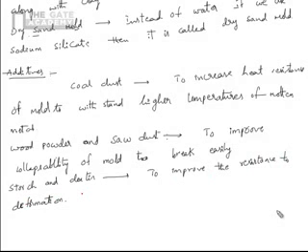So these are the mold materials which are necessary to add along with sand. Water and clay are essential, you need to add them. There is another type of mold besides sand molds. For metal molds you don't need to add anything. Metal molds are used for very special purposes, very rarely, and those are different types of casting. If you use metal molds, those are called die castings. That is discussed later, but first, more importance is on sand molds.